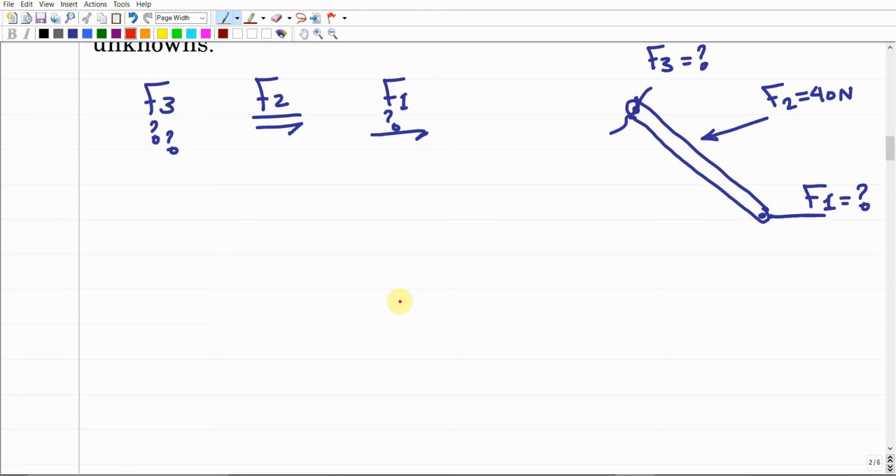So how it works, how we can draw the force polygon for this mechanism. It is very simple. We're gonna start as we used to do even for the graphical method for the position, velocity and acceleration analysis. We have to start with a 0 point, the origin point of the force polygon. So I'm gonna use another color here for generating this force polygon. Let us assume that this is the point OF. This is the origin point, the 0 point of the force.